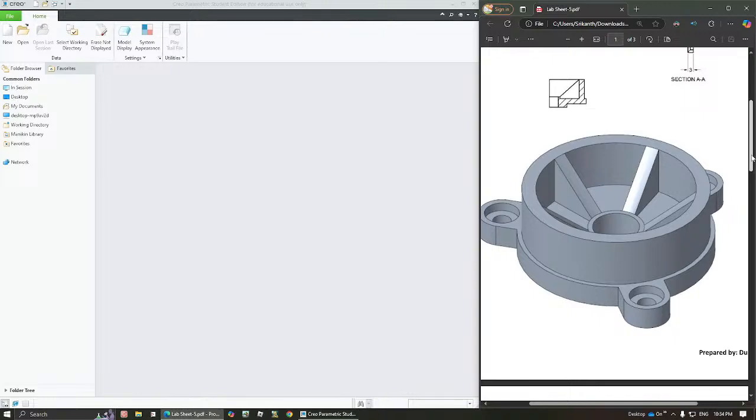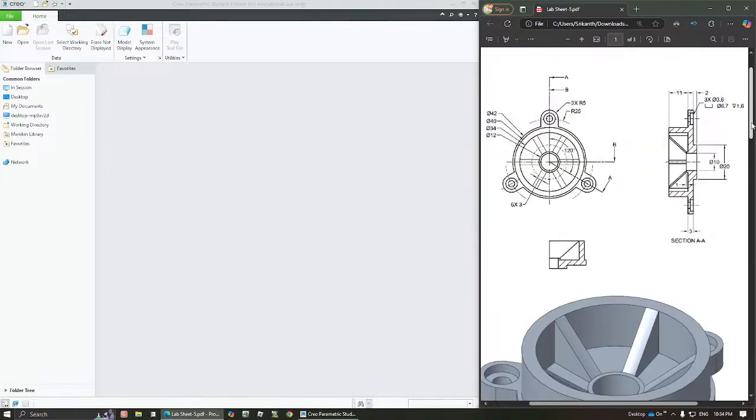Now if you look closely, there is one error, one difference between the 3D model that we have been shown and the views that we see at the top here. The counterbore holes that we see around here are facing on the right side, in spite of this being a third angle projection, when we see from this side, it is supposed to be visible over here.